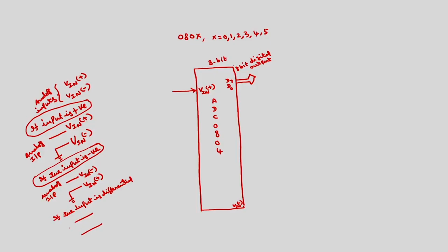Here I will connect the input signal, plus to plus, minus to minus. Here I am assuming that V in minus I am going to ground along with some other signals, means that I want to use it only for positive signals. V in input signal is positive.